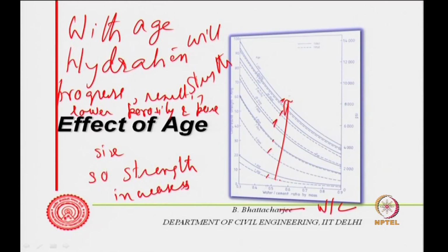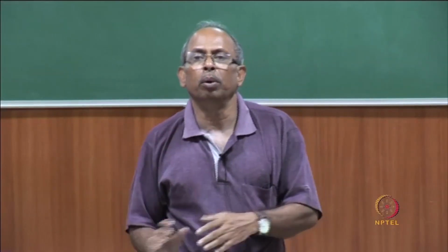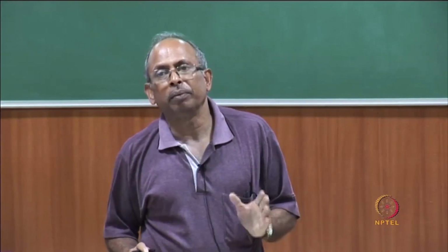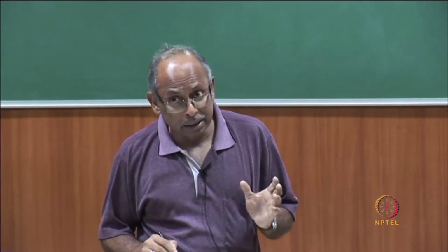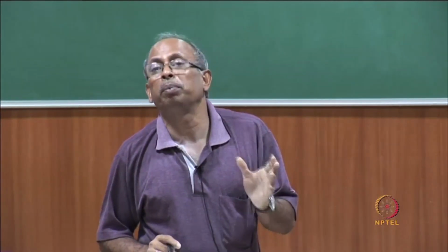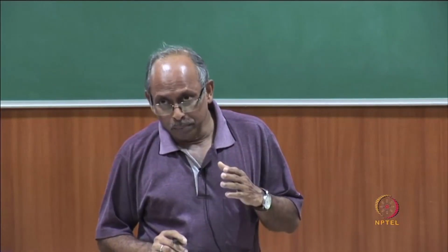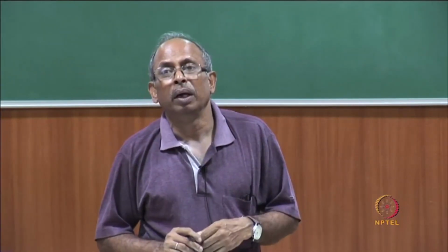Now, hydration itself is a function of course of water cement ratio, but as you can see, this effect is quite prominent in low water cement ratio, but even high water cement ratio is also fairly prominent. In low water cement ratio, hydration possibility is actually more, but then of course, there is a range, 0.4, 0.3 we are talking of, beyond which full hydration is never possible. We have discussed this sometime earlier, that full hydration is not possible below certain water cement ratio, right, but does not matter.